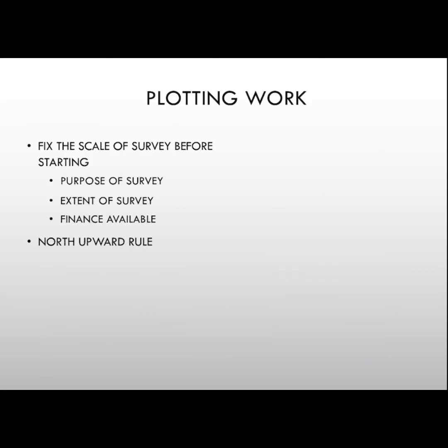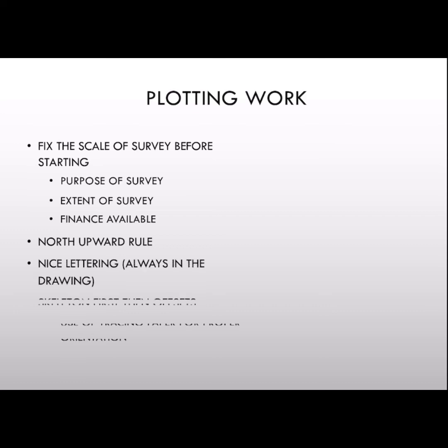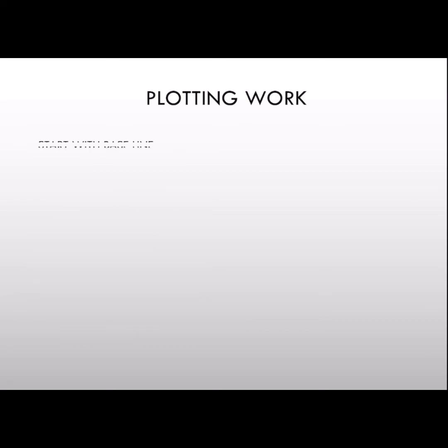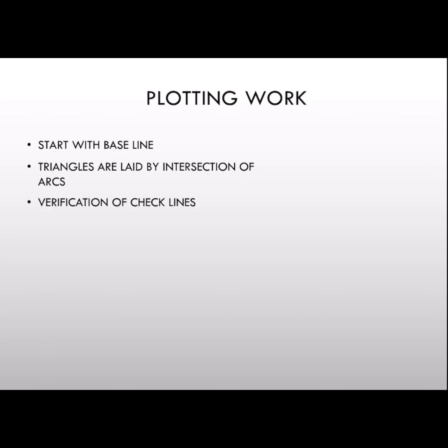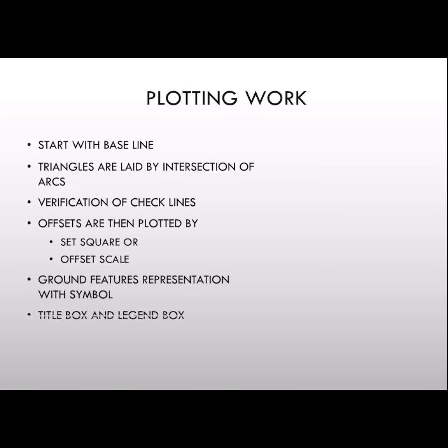Plotting work: fixing the scale of the survey before starting, depending on the purpose of the survey, the extent of the survey, and finance available. Neat rules, like nice lettering always in the drawing. Skeleton first, orientation. In the plotting work, start with the baseline. Triangles are located by the intersection of arcs, and the verification of check lines and offsets are then plotted by the set square or offset scale, along with ground features.